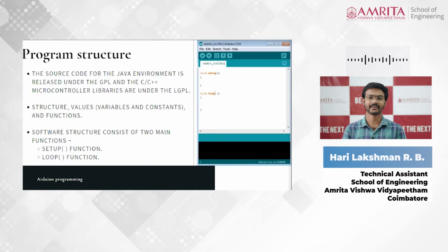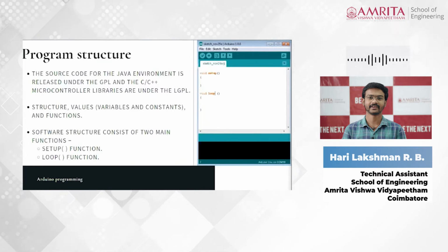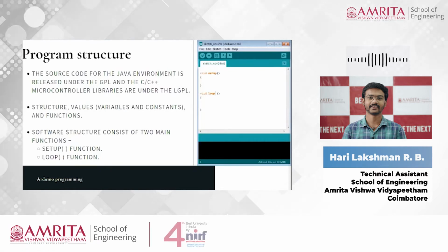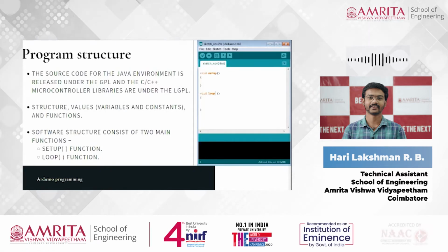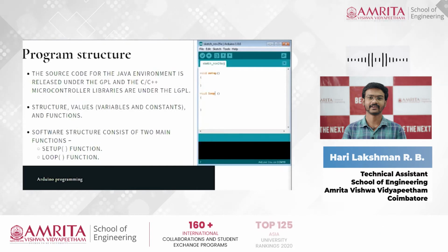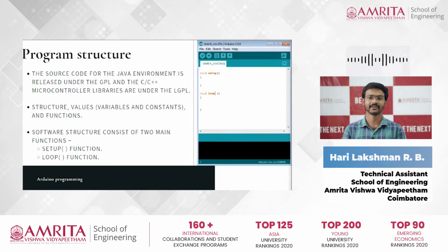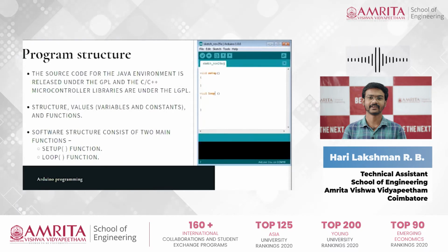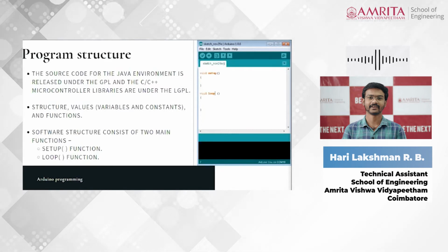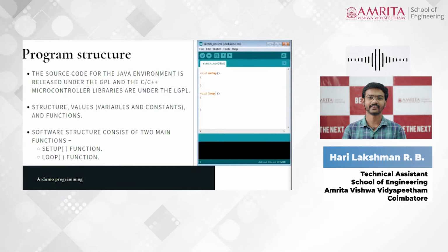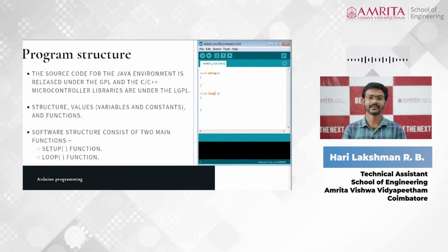And inside the void loop, after creating the setup function, which initializes and sets the initial values, the loop function does precisely what its name suggests. It loops consecutively, allowing your program to change and respond. So use it actively to control the Arduino board. Even in the void loop, you can use any kind of functions and inputs, outputs. The void loop does not run only once, it is a loop function, and it goes on until you give an end code.